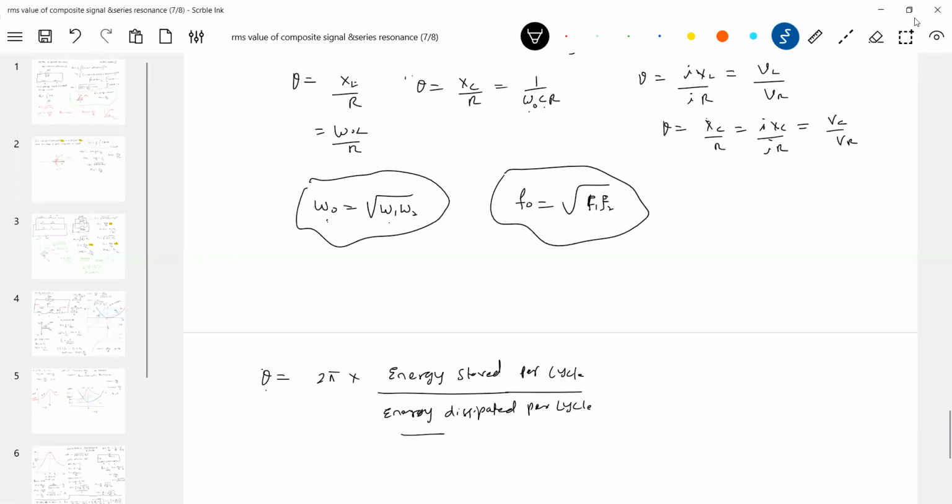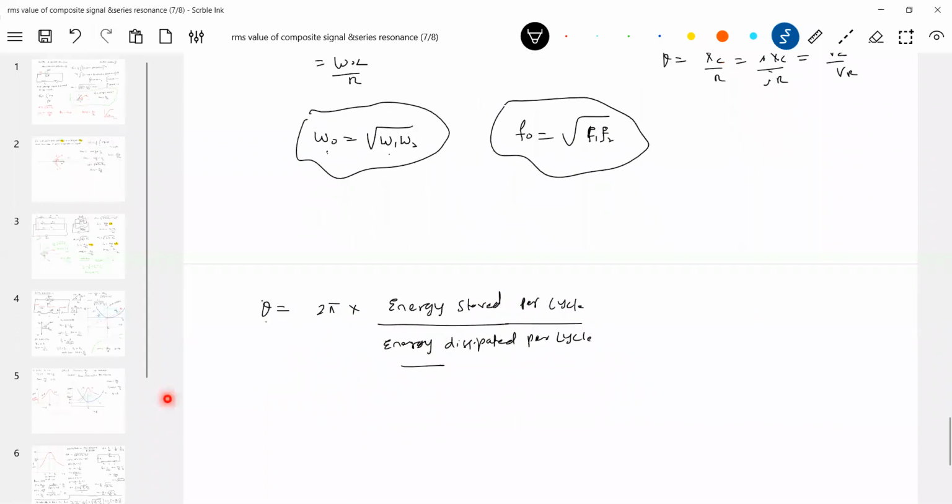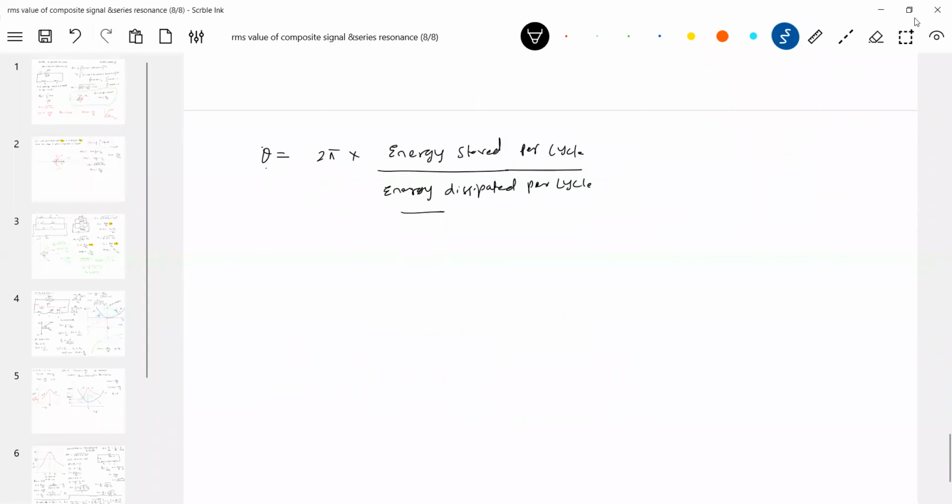So this is about the theoretical thing, we are learning it only in a mathematical way. When we go to the communication chapter, there you are going to learn it in detail. So the quality factor of that RLC circuit matters a lot. So I'll suggest, what is the actual meaning of this? Suppose this is an antenna. The antenna wire will have a resistance.